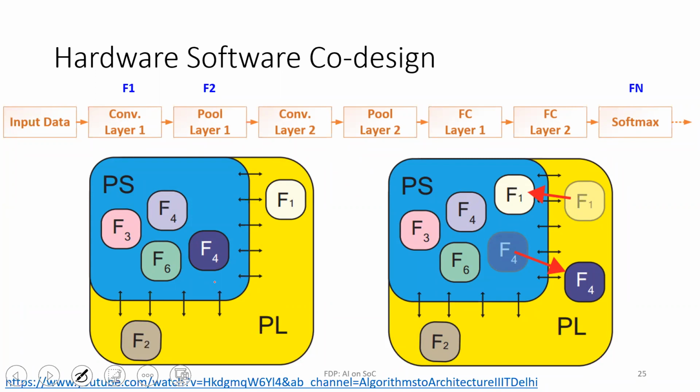Whatever you want to implement on the PS, there are different approaches. You can first deploy an operating system on the PS and then write an appropriate application for it. Or you can do bare metal code. You can write normal C++ code, or even Python code, and implement your algorithm on the PS. So there are multiple ways to do the mapping.